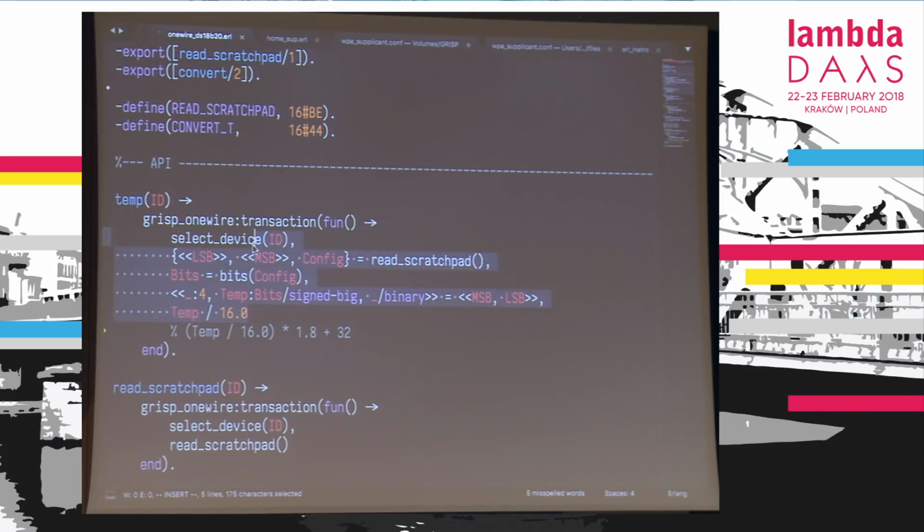And this is basically how you get out the 12 bits of temperature value from the sensor data. Because it is in total 2 bytes, 16 bits, we divide it by 16 in the end when we get the numerical value to actually get the degrees Celsius, because the sensor gives us degrees Celsius. That's how it's made. So if you wanted to change this, for example, to Fahrenheit, we could update the calculation.